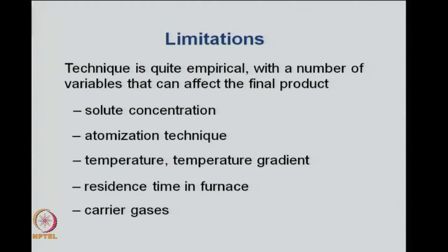There are many carrier gases, and each of these factors, solute concentration, atomization, temperature, gradient of temperature, residence time, and the nature of the carrier gases, all of them will affect your ultimate product size and size distribution, and we have to fix our parameters if we want to fix the product.